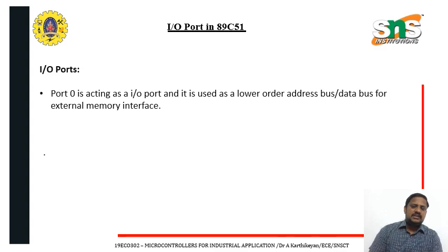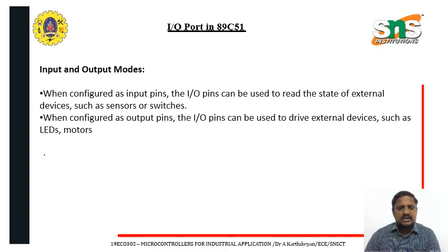The port acts as an I/O port and also carries the lower order address bus and data, allowing an external memory interface. We especially use this I/O port for external memory interfacing. When the I/O pins are configured as inputs, they can be used for read and write operations with external devices such as sensors, switches and other peripherals. As outputs, the pins can drive external devices like LEDs, motors, monitors and other peripheral devices.